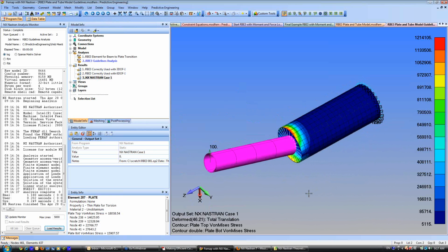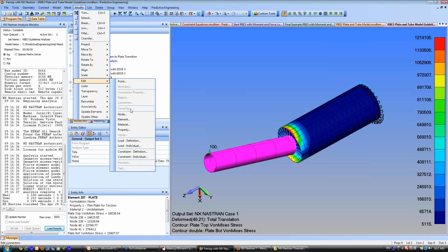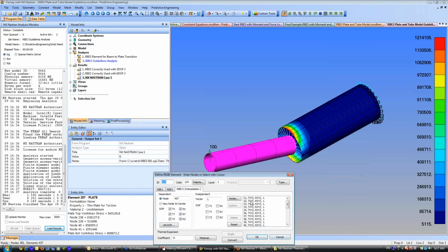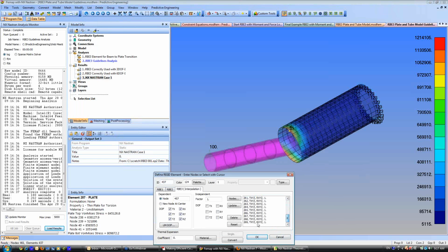And the reason is that when it's forming a matrix inside, and when you over constrain it with your RBE3, it can't figure out what to do. It just basically blows up mathematically internal. It solves, but it's just lost.